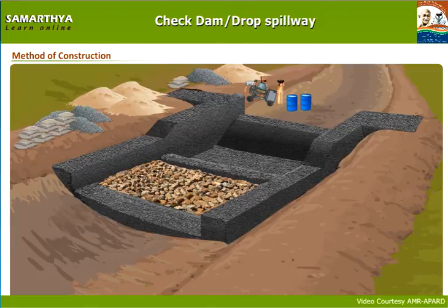Fill the gaps between the stones in loose apron with gravel to see that there are no gaps. Water curing must be done to all concrete parts for 21 days to maintain moisture.